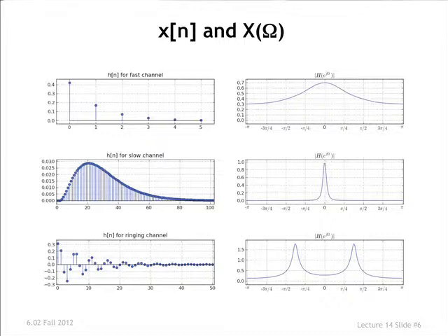Here's another example, a signal that, in this case, seems to have some fairly regular periodicity to it, and then it damps out. By the way, in all these cases, I'm assuming the signal's identically zero outside of what I've shown you here. If you take the DTFT of this, you find that the spectral content is what? Low frequency, mid frequency, high frequency? Mid frequency, right? Because this is low frequency here, 0. This is high frequency. This is just a reflection on the left side. So at some intermediate frequency, there's a peak in the spectral content.